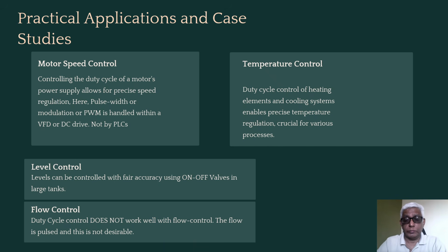But let us be clear, this is not a PLC function. That is done by the drive, like a VFD, that can synthesize any frequency up to 400 Hz using millisecond switching times. That is done in the VFD, not PLC.